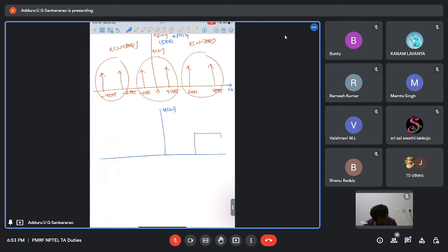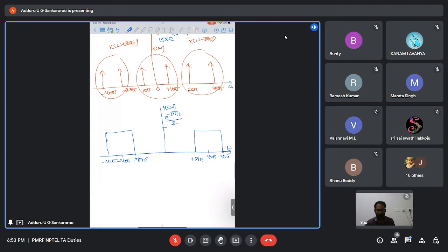You have a band pass filter: 40 pi, 41 pi, 39 pi. Similarly here minus 40 pi, minus 39 pi, minus 41 pi, and we have this phase e power minus j pi by 2. Okay, this is H of omega. Now you tell me, we have x delta of t and H of omega. Now what frequencies will go out of the filter and what frequencies will be suppressed? Can somebody tell me?